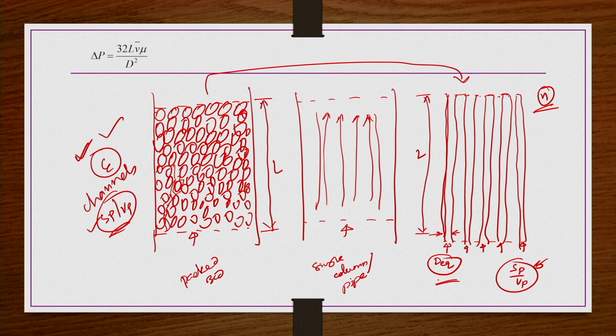That is what we are going to do. Okay. And then in the Hagen-Poiseuille equation, wherever d is there, we replace d by d equivalent, and v we replace by the superficial velocity v bar. So, v bar is a kind of superficial velocity of the packed bed.